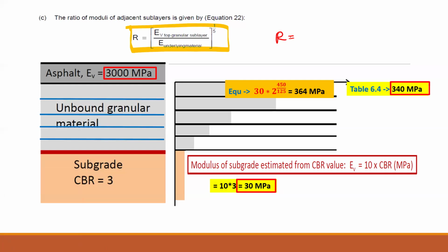It's not the asphalt layer. The top sublayers are these 5 sublayers. Granular, they're talking about granular, not about the bonded one. Do you understand the differences? This is granular, not bonded. This is asphalt concrete, where we have bitumen and aggregate. It's not concrete, but instead of cement, we have used bitumen. This is a native soil.